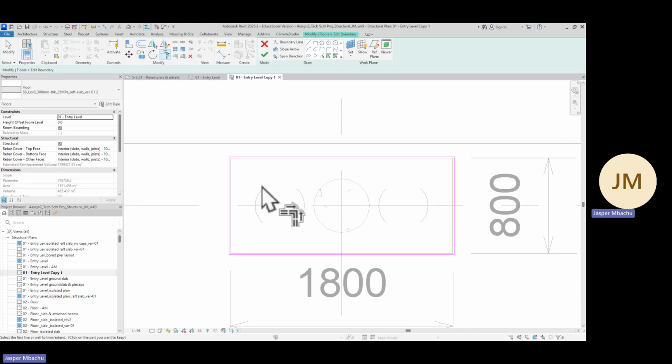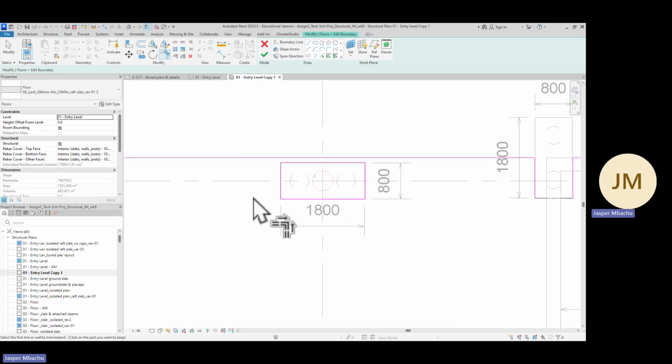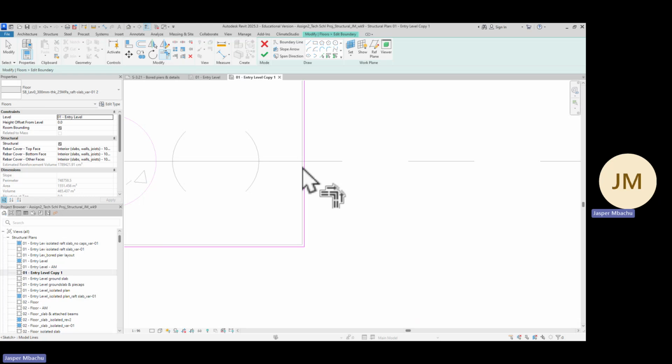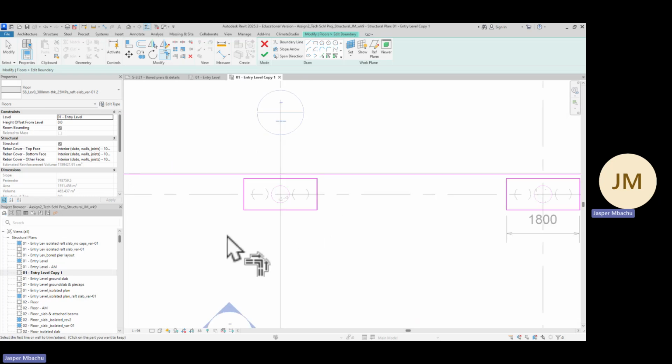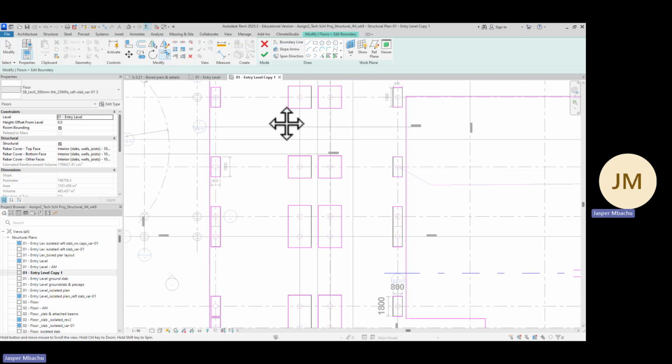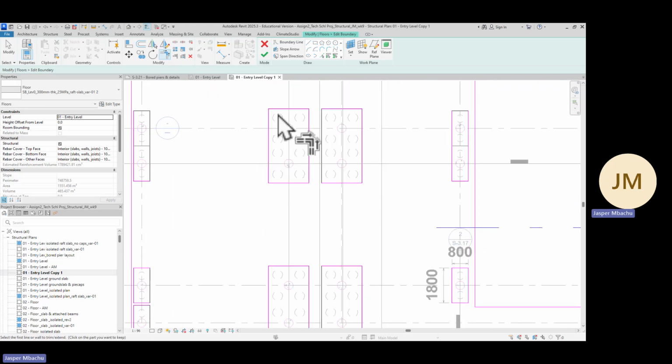There's a way they do it so that there could be slight separation. But just make sure you have 10 mil gap isolated using this principle all around your pier cap. All right. Now this side, you can do it the way you did it before.